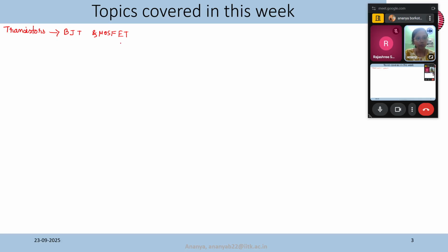There are a few fundamental differences between BJT and MOSFETs. If you are interested, you can learn about it. There are certain applications where MOSFETs are more useful. Many times for switching applications people prefer MOSFET, and in circuits where we need low power consumption, MOSFETs are useful because we know that in CMOS technology the power consumption is less.